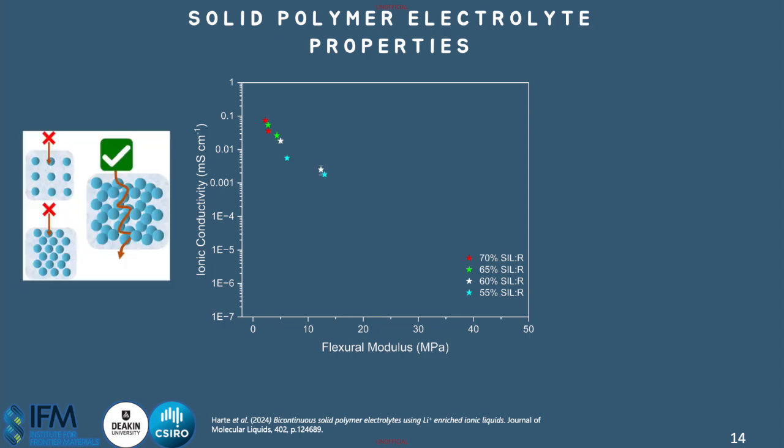However, there is a limit to this, and you can see here that when we tested the 50% samples, it was quite clear that the drop of ionic conductivity by more than 3 orders of magnitude was a result of being below the percolation threshold in the electrolyte system, where basically the conductive channels within the electrolyte were not connecting efficiently, and that explains the significant drop in ionic conductivity.